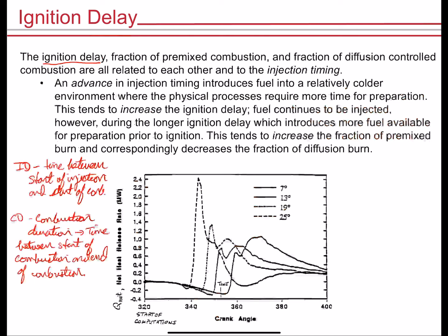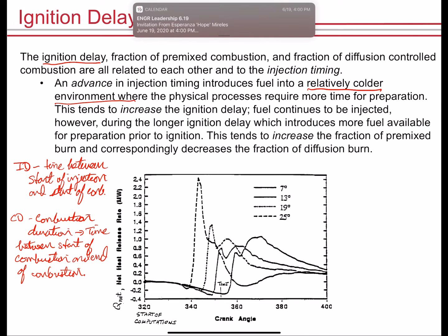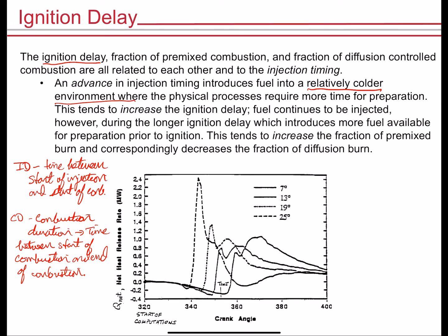Okay, and how does injection timing play into this? Well, generally speaking, if we advance injection timing, when the injection timing is still before top dead center, then we're introducing the fuel into a relatively colder environment. Remember, think about this physically. The physical processes are penetration, breakup, atomization, and vaporization, right?